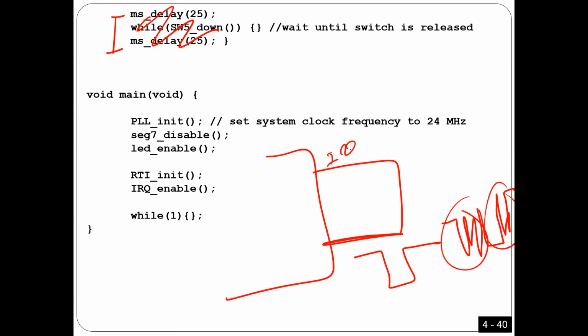So if I connect it to IRQ, when you press one time, you are not going to make one interrupt. I'm going to make multiple interrupts. So you can try it tomorrow. Just don't write the debouncing code and see what's going to happen. By the way, maybe when you remove this code, it's going to work, and you'll say, you told us it's not going to work, but it's working. You know why? Because, as I'm going to explain in chapter 3, there is what we call a hardware solution to the bouncing problem. For sure in the old boards, the blue ones, and I think most of you don't have this one, I'm sure there is no hardware solution. That's why we have bouncing there.